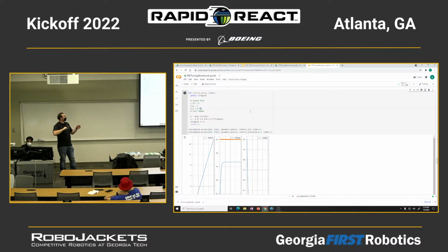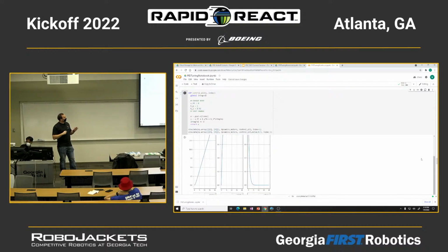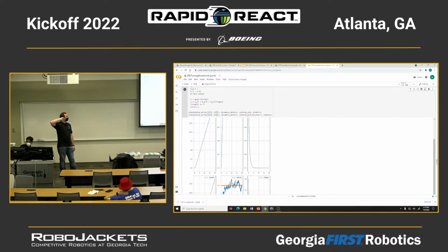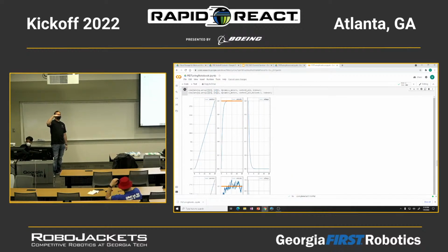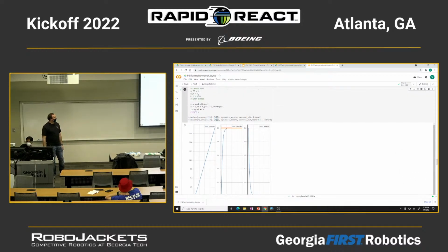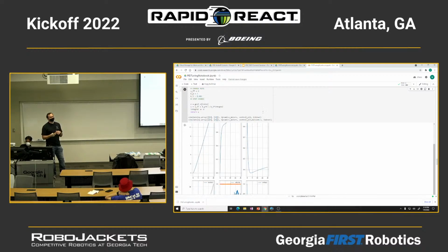But if we add an I term, you'll see that it'll actually reach that set point. Because now we have this accumulated error, so over time, as we continue to sit at this cap-out point, it'll slowly push us up. This one's a little bit more aggressive, so it does it almost immediately. But this will handle any steady state error, as we talked about. This would be something like friction as you were driving along.